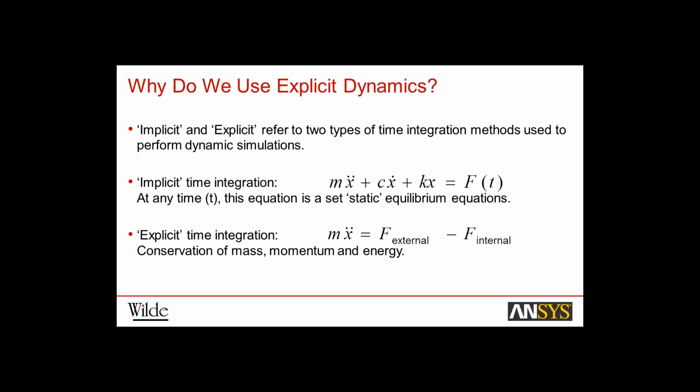Thank you, Brian. So the first thing we're going to look at is we're going to distinguish between the two types of finite element analysis approaches, comparing implicit and explicit types of analyses. In this case, implicit and explicit refers to the two types of time integration methods used to perform a dynamic simulation.